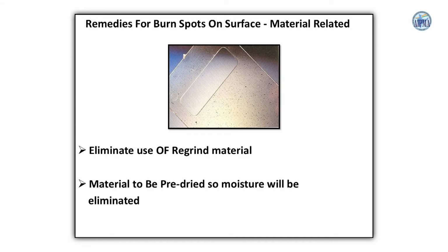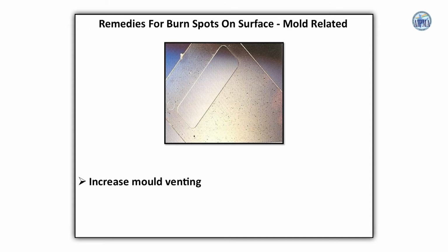Remedies, raw material. Eliminate use of regrind material. Material to be pre-dried, so moisture will be eliminated. Remedies, mold. Increase mold venting.